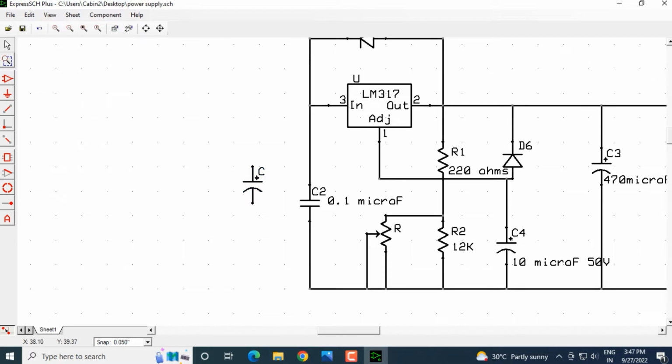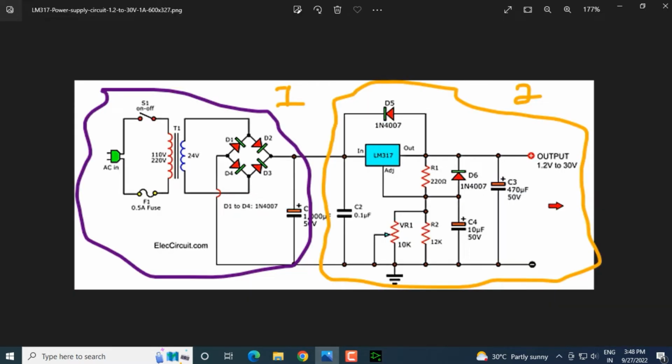And now I'll insert the wire. So I'll place a wire and bring it here. Connect it over here. Then I press the space key so that the wire is connected. Same thing here, I'll connect it. So this part of the circuit is now almost complete, and so this part now remains. We need a bridge of the diodes whereby the two cathodes are connected and two anodes are connected.